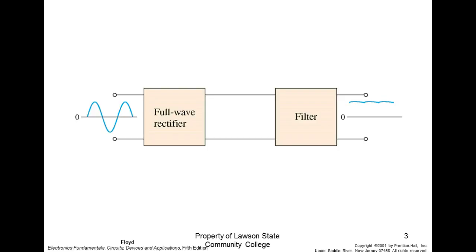Change the... it varies with the load or it varies with the input. Yeah, it varies. If your input voltage changes, the output will change. If your load changes, the output will change. So, yeah, you can unload that thing and put a capacitor on it, and it'll be perfect DC. It'll be beautiful. As soon as you put a resistor load on there, the output's going to drop down, and then you'll see that ripple voltage.